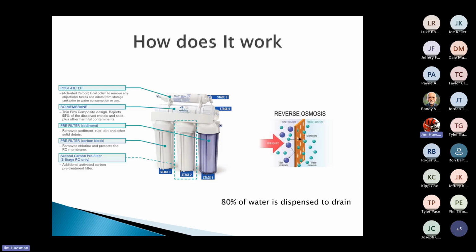And knowing this, just remember, between 75 and 80% of the water that you're running through your RO goes to drain. You only hold on to about 20 to 25% of your water, okay? So if I'm dumping 100 gallons into our tank, remember, I'm only getting a 5-gallon bucket out of it, okay? Because most of the water is made up. We've got a lot of stuff in our water that's not bad for us, but with RO, we want it all out. We've decided for some reason we wanted everything out, okay? But once it gets to that membrane, we're good.